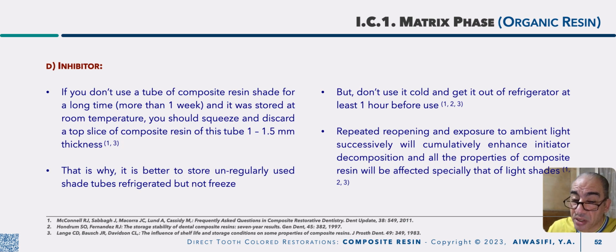Otherwise you will need to increase your curing time to compensate for this delayed initiation. And it is preferable to squeeze 1 to 1.5 millimeter slice and discard it, because this first slice is either oxygen inhibited or started to be affected by the ambient light.